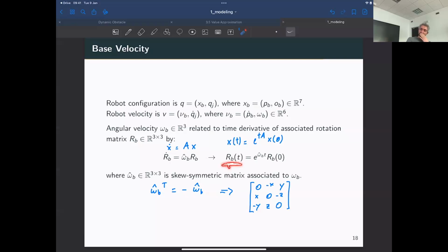I know that there are situations in which quaternions are faster, and situations in which rotation matrices are faster. I think that if you need to apply a rotation to a given vector, the rotation matrix is the fastest, because you have just to do a matrix vector multiplication, whereas for the quaternion, the expression is a bit more convoluted, so it takes some nanoseconds more.